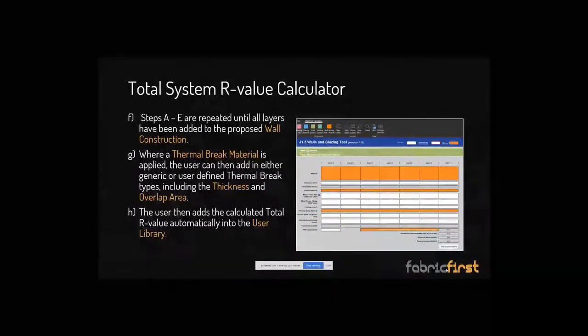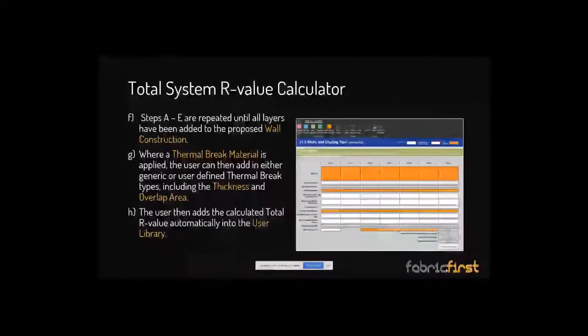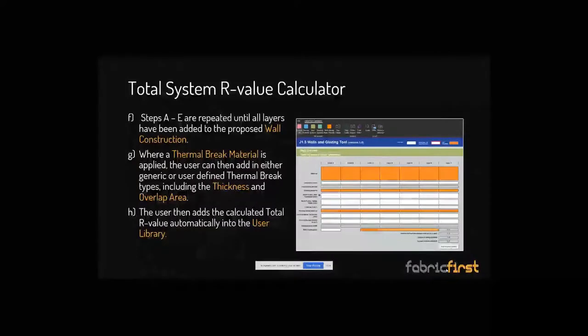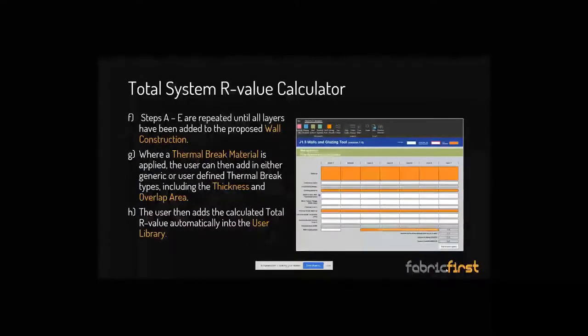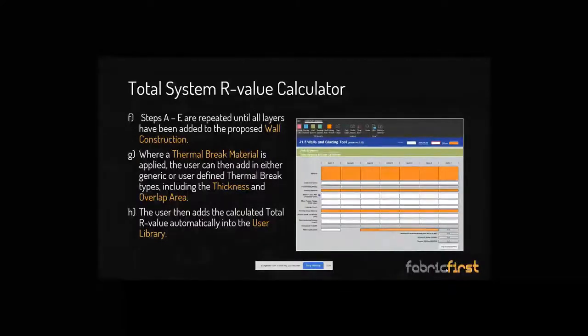So there is a second level to this calculation. It's from this orange line here. And this is where you say, okay, I've got a steel frame here, it's in my glass wall. What can I use to break that steel? So you can nominate a product. At the moment, we can nominate EPS, but EPS is combustible. So we can't nominate EPS, but that is really our only option at the moment. So there is a dilemma out there, because how we actually treat it is going to need to be outside of combustible products. So obviously there's always ways around these things, but that is the way things are at the moment.